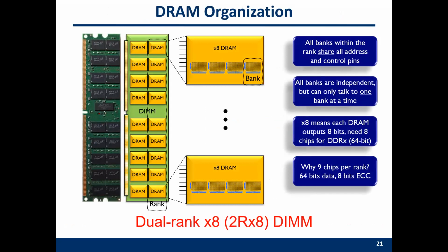So this is the physical layout of your DRAM. This is the so-called DIMM, D-I-M-M. You have a lot of DRAM chips on the DIMM, and each chip has a lot of arrays. We also have ECC. Some chips store the ECC. The ECC can protect against bits accidentally flipped because of radiation.